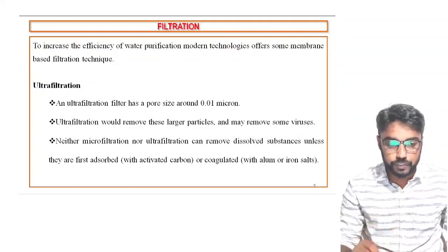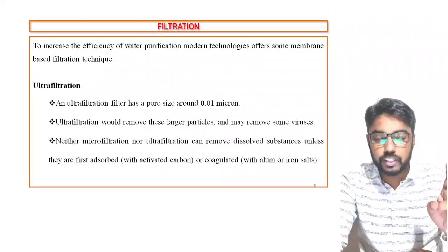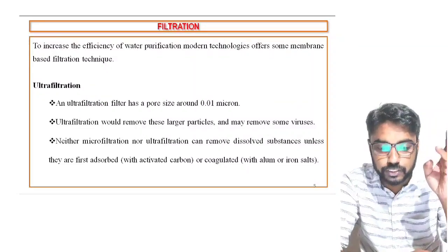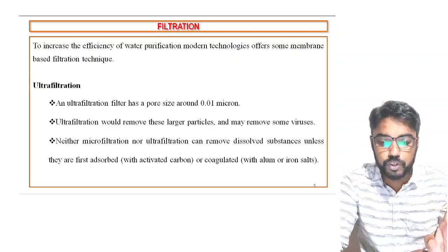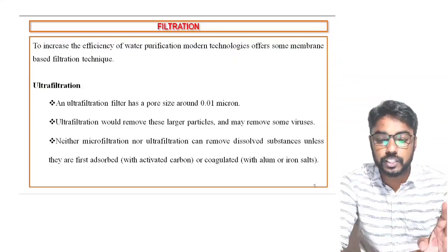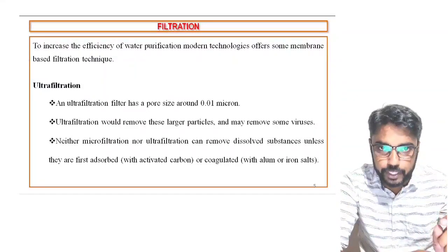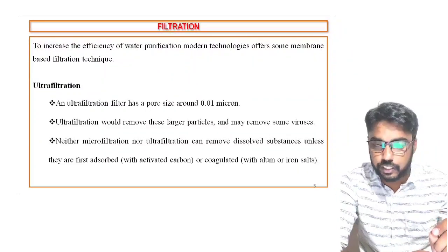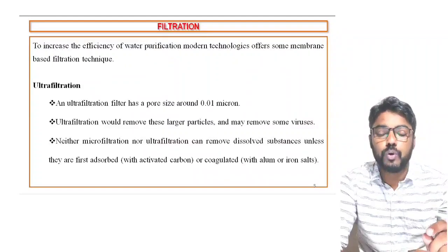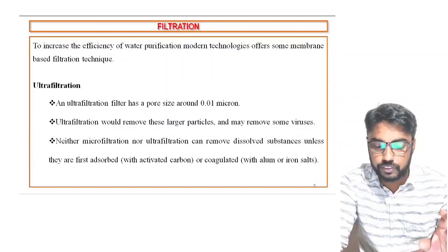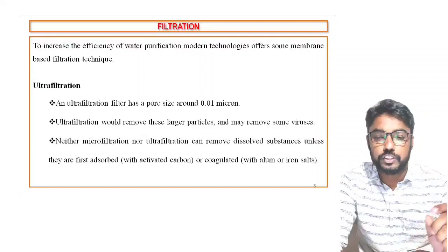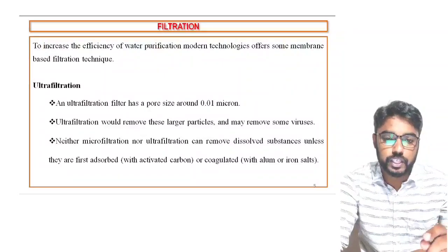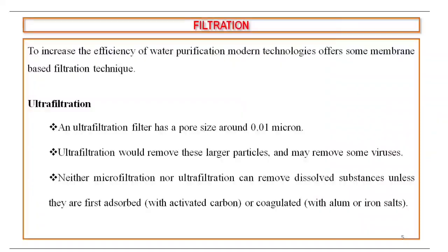Okay, this is about ultrafiltration. Ultrafiltration has a pore size of around 0.01 micron, and it would remove large particles, and sometimes it can remove some viruses. Neither microfiltration nor ultrafiltration can remove dissolved substances present in the water. Okay, this is about ultrafiltration.